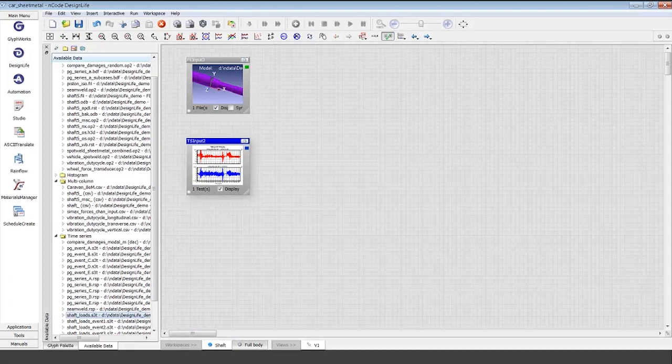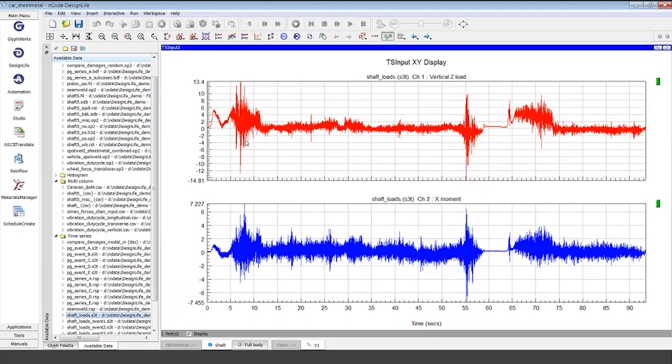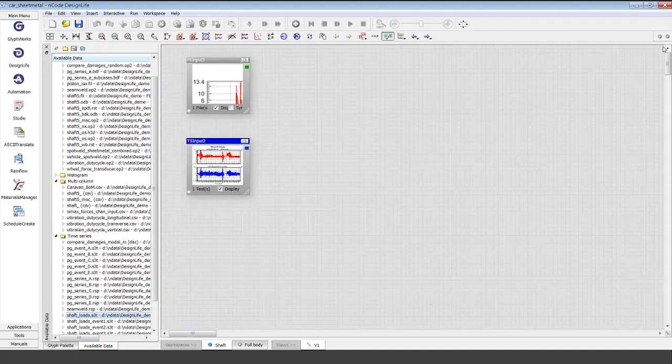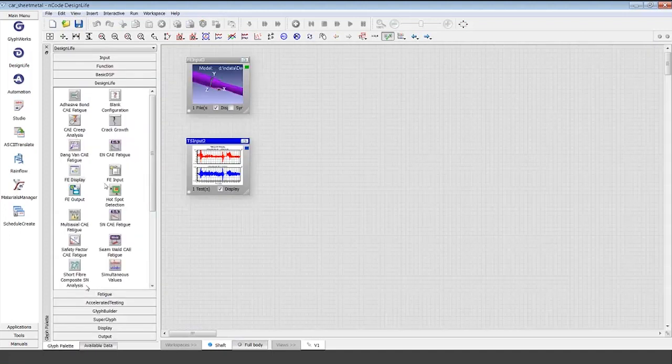And so this is the component of interest. This is the loading that we want to associate with the stress solution in FEA, and this will cause stress cycles. So let me just pull that together into a fatigue calculation glyph. I'll use a StrainLife glyph, which has lots of neat features in it for looking at plasticity corrections and cycle counting and all sorts of neat stuff like that.